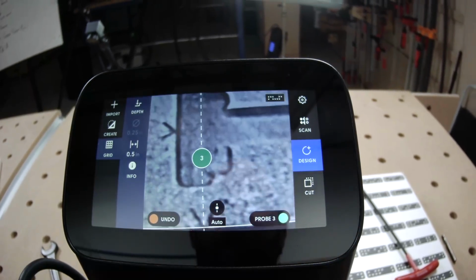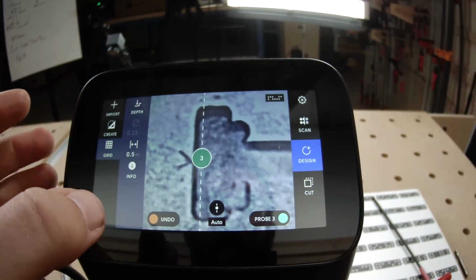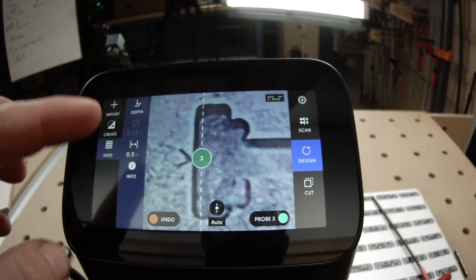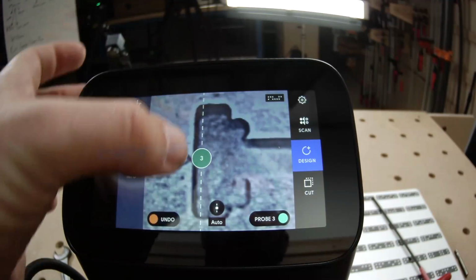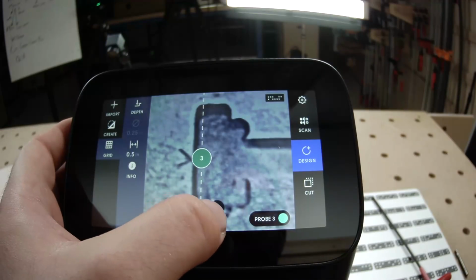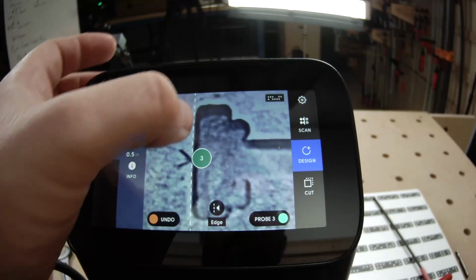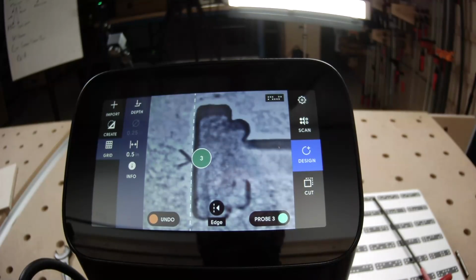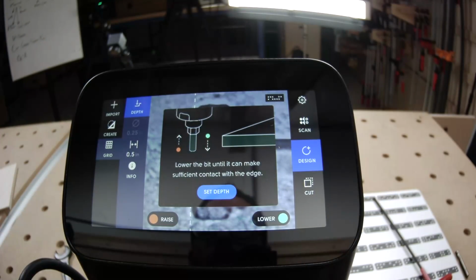And then I'm going to just lift this up so that I can get into this pocket and probe the y-axis here. Now note that right now, since I'm in between my 2 x probe points, the origin automatically makes the center, this y-axis probe point, in the center of the probe, and that is not what I want for this application. I want it on the left side because I want that to line up with this edge. So you can just change that with this on-screen button down here. And if you wanted to adjust the height of the pin on any one of those probes, you can go right back into depth here and raise and lower.